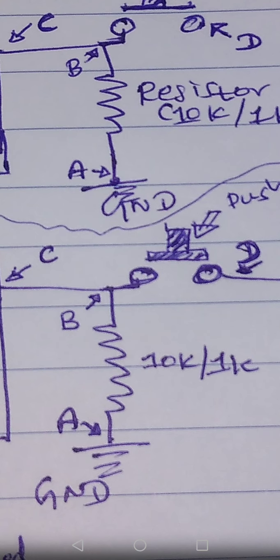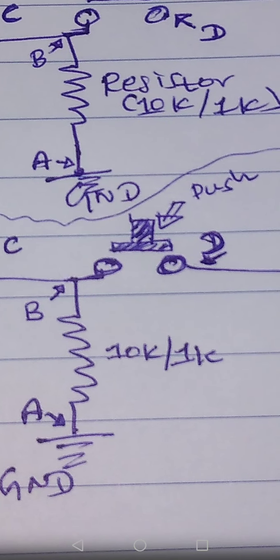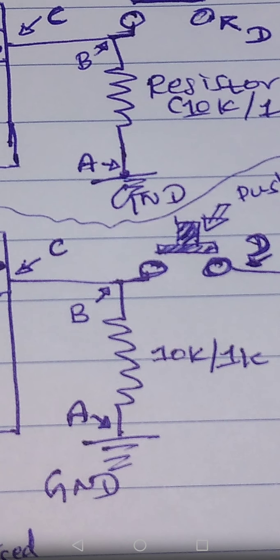And if you remove that button, that +5 connection is now terminated. If you release the button, D will be +5 and B will again be ground, because there is no connection and no current is running now, because no 5 voltage is coming to B point. So B will remain as ground, like the initial state.